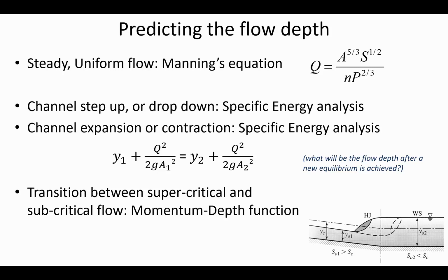Okay, next, here in Chapter 13, we're going to look at a different type of non-uniform flow. And just as an illustration, what this figure is showing is what if we had two different channel slopes coming together. We had a steep section of a channel that matched into a relatively shallow channel section. And in this steep section, it was steep enough that the flow is going supercritical. And so the Froude number is greater than 1 when it's supercritical flow.